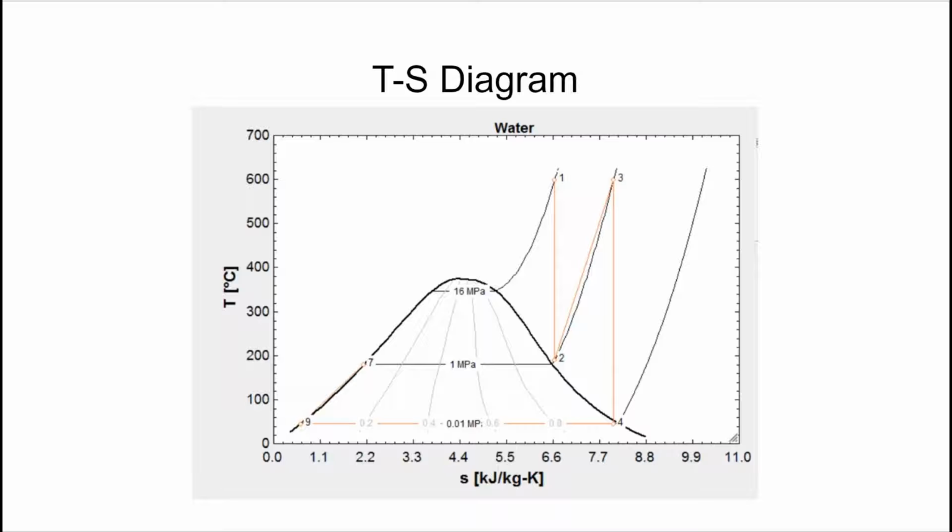This diagram is based on the pressure coming out of the boiler at 16 megapascals, since that's the value that gives us the highest efficiency in workout and does not exceed our limits. Our flow of water throughout the cycle changes accordingly and follows a correct Rankine cycle.